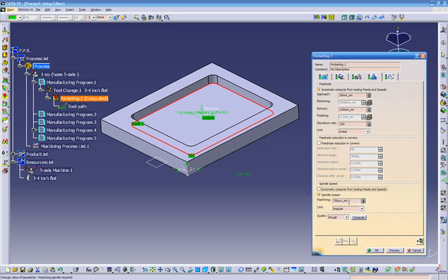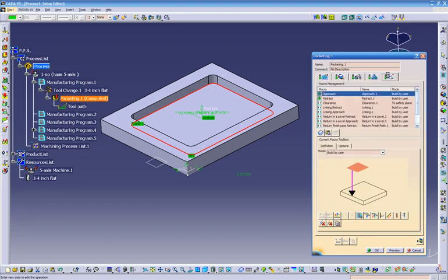And this is our RPM. So for the 3/4 end mill, if we have a carbide, we'll usually go around 6500 RPM. And let's put the quality of this program finish. We want a nice finish on this part. Let's go to the last tab, feeds, the way we lead in and lead out into this part.